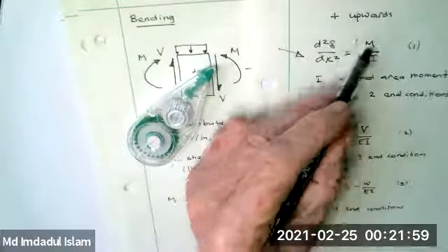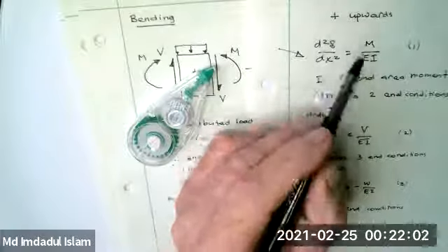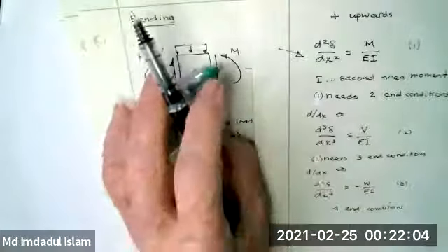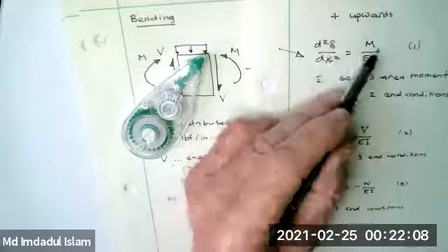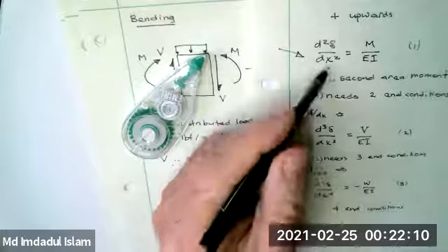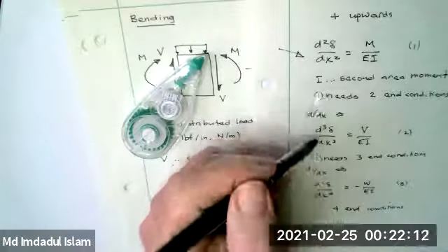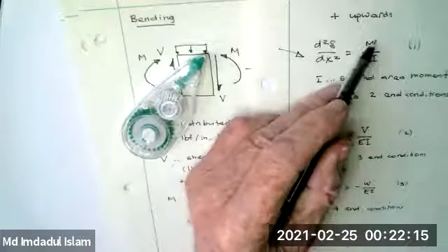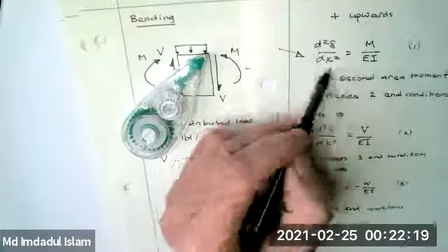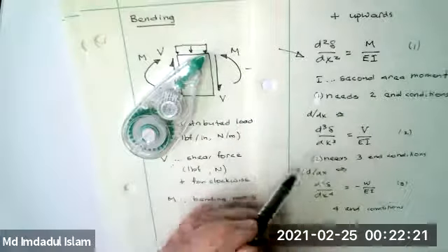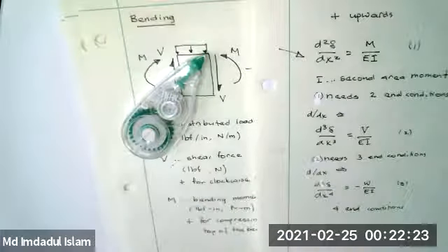You want to get good at getting bending moments. Bending stresses are what break things in mechanical engineering for the most part, and so you need the bending moments. You're better off just learning how to do it. Now, this is an alternative approach. If you do it accurately, it will work, okay? But you're better off developing physical understanding of M and integrating it twice. That's what we're going to focus on here, is using this. That's not to say you can't use these others, okay? And so we'll start doing some more of that next lecture.